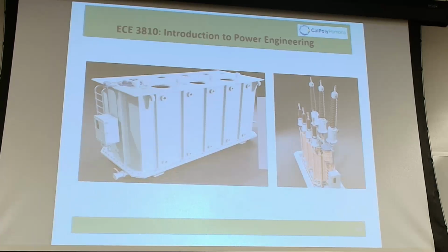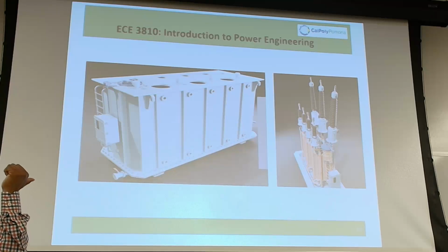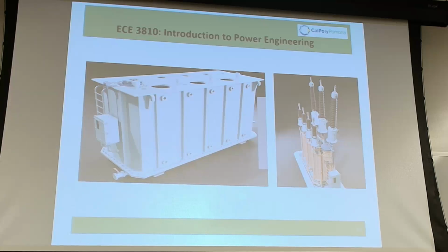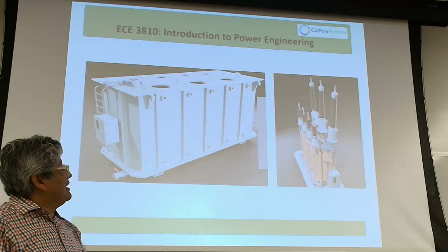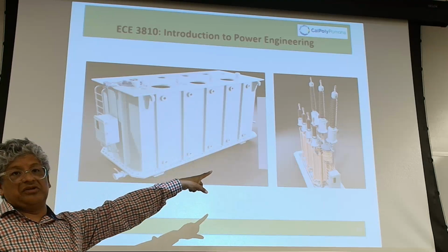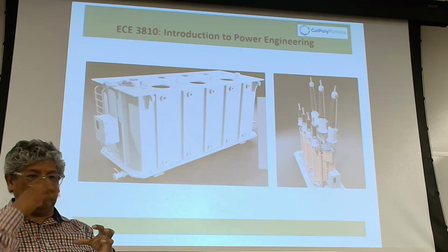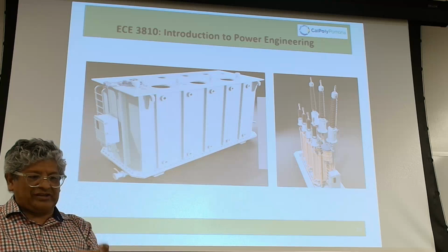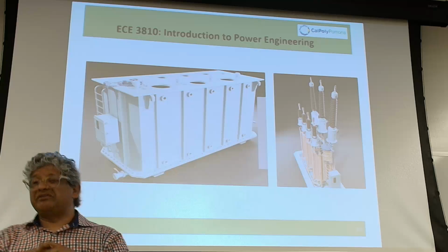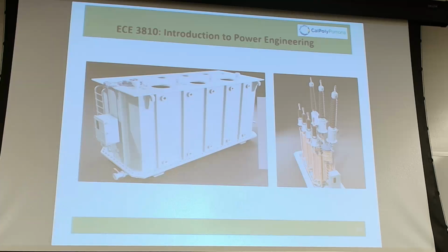Oh, by the way, I said the tap changer is the one piece that transformer manufacturers don't manufacture. That's another one they don't manufacture. They buy it from companies, but those companies are very well established. As a matter of fact, for the current transformers, to make sure current is going in and out, in some cases it's built into the insulator. There is a donut, a core, a current transformer built in there, so it's built into the transformer insulator.